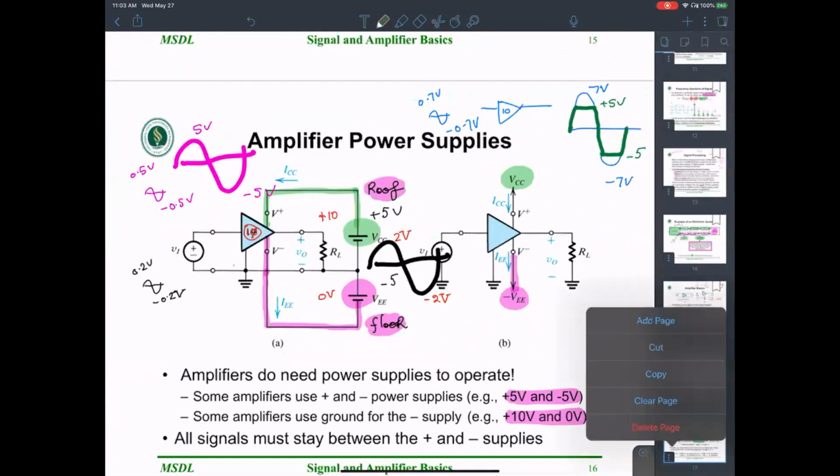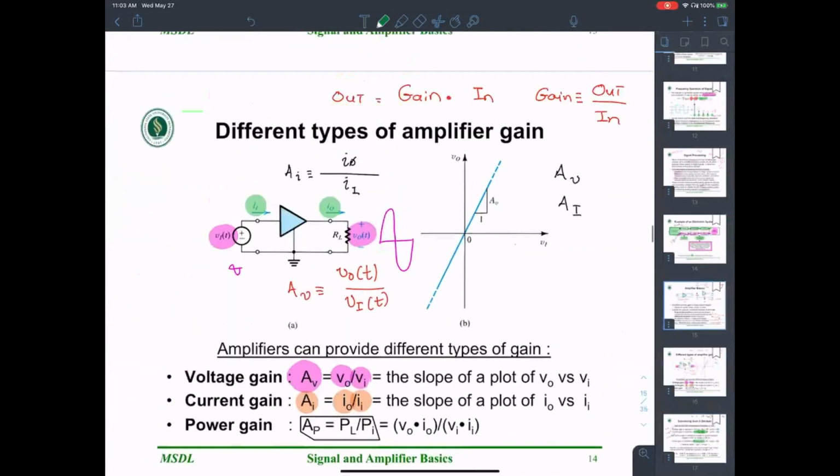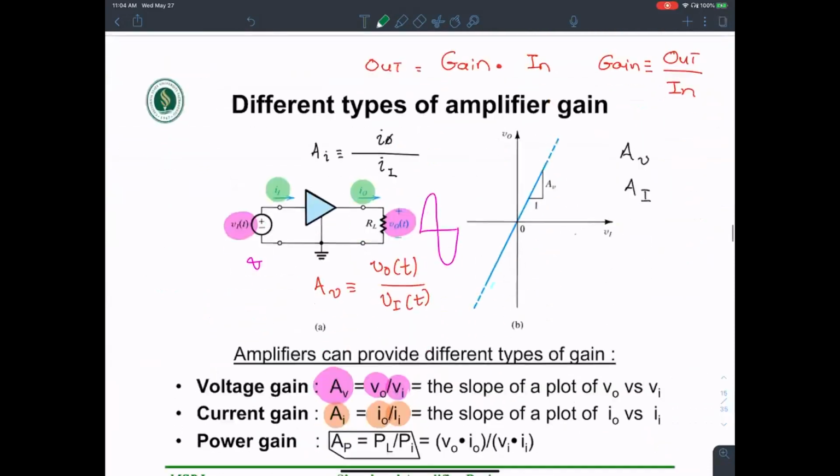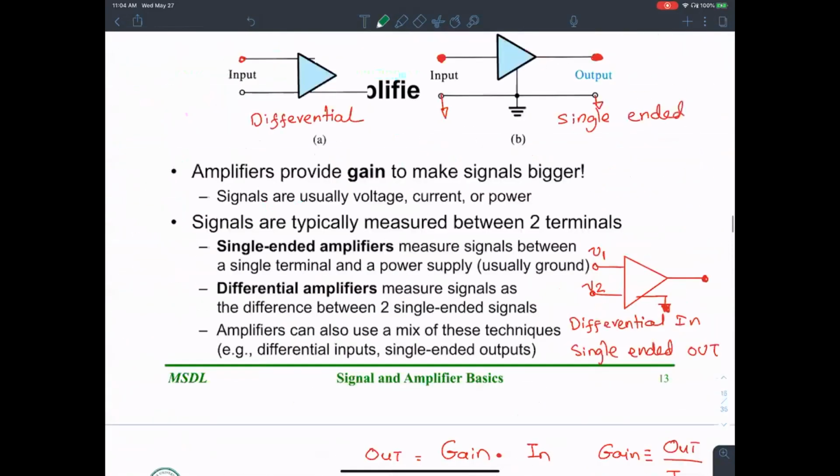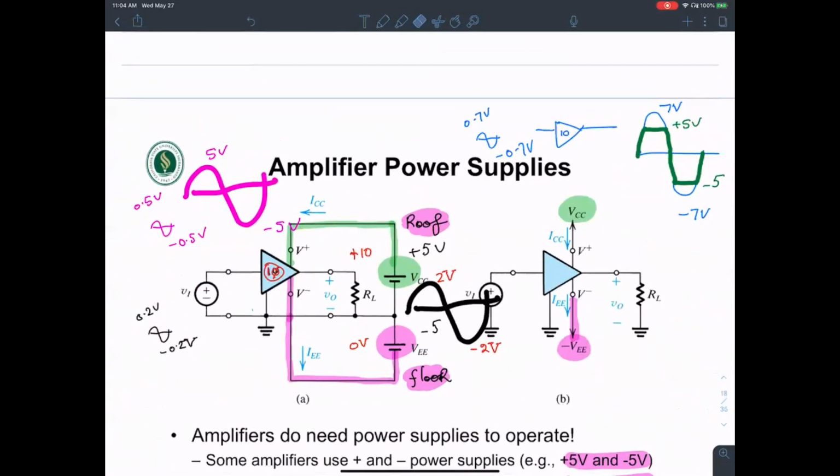Questions, please. What happened to the flat area, the part that you chop off out of that sine wave? Yes, in the flat area, right here, that's how your output is going to look. When the input is really, really small, remember 0.7 to negative 0.7, the output is going to be flat, 5 volts. Will that distort the signal you're trying to amplify? Yes, what happens is this node right here will show a value of 5. So in other words, I'll tell you what.